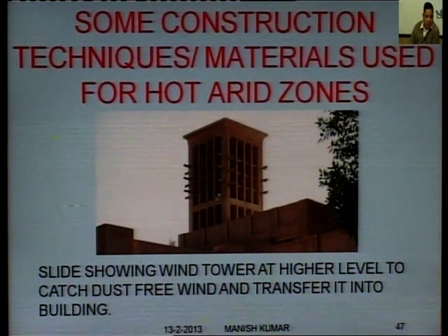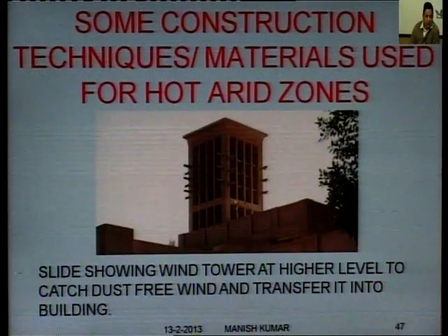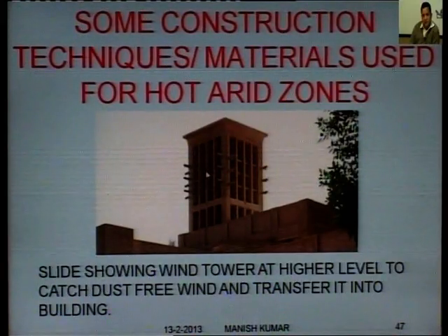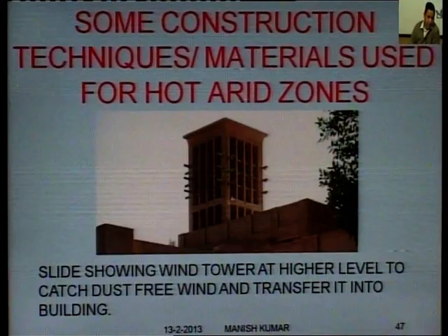These towers can be provided with some sort of water source or water sprinklers inside. So hot dusty wind will travel from these inlets, go through some sort of water sprinkler inlets, and the air received inside will be a little cooler and dust free.